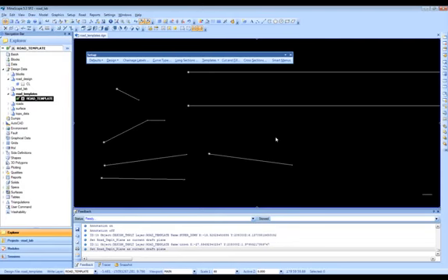The other thing about templates, and what we allow you to do, is you also have edge templates along the road. If you're in a cut situation, what kind of look do you want to have, versus if you're in a fill situation at the edge of the road, what you want it to be. So, for example, if you're in a fill situation, you might, by law, have to have a bit of a berm, a safety berm, of sufficient height to keep people from running off and down over the side slope.